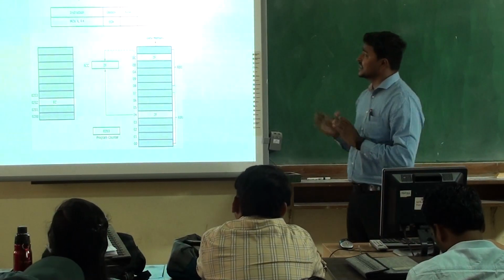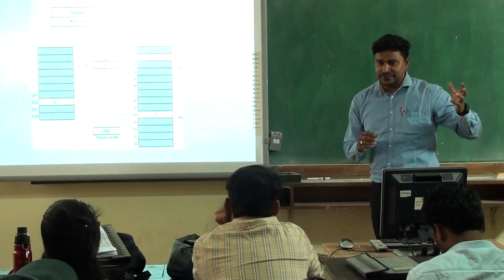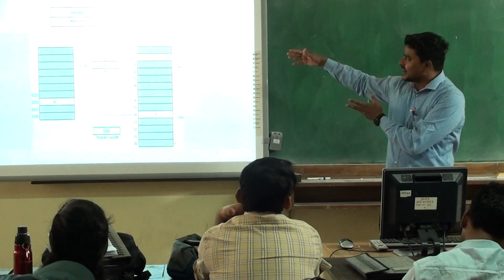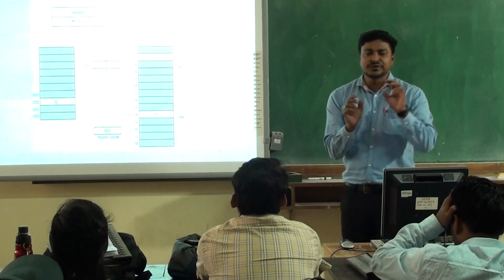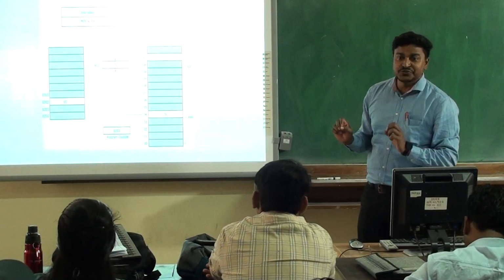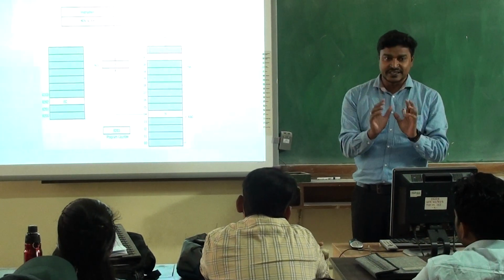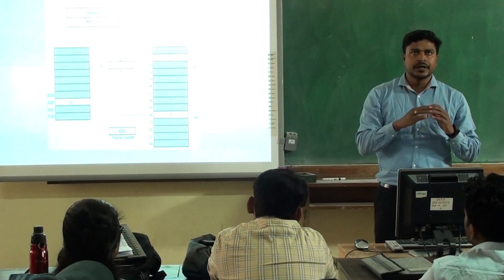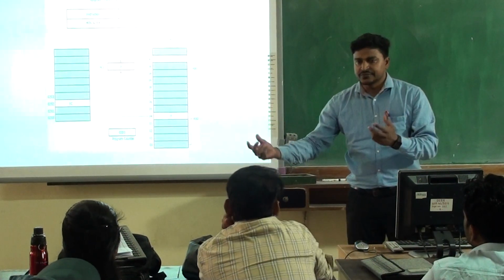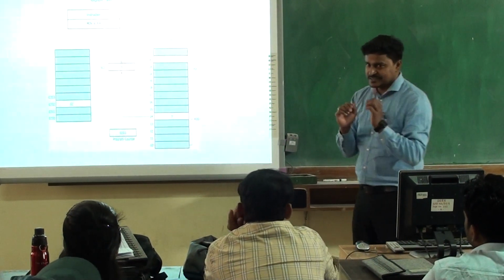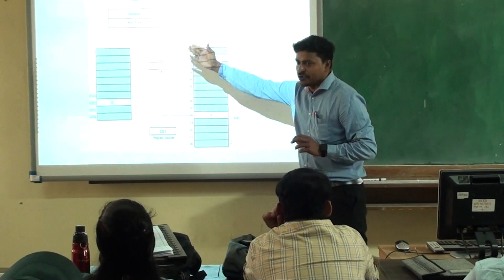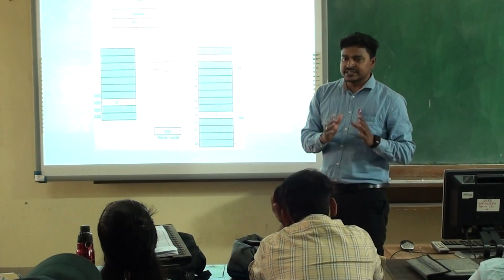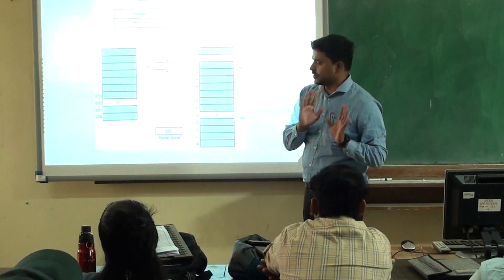So this is your register addressing mode. In the last addressing mode, the direct addressing mode, we were choosing some location in memory. But here we are choosing some register, a general purpose register, not some arbitrary memory address, like R4. R4 is a general purpose register in the RAM of the 8051 microcontroller.